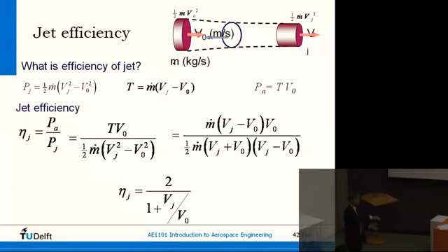And that's why these engines have become bigger and bigger over time. The large diameter is caused by the jet efficiency. And of course, then we say we do this to avoid noise. We do this for the people living around the airport. Oh, by the way, we got a nice high jet efficiency.